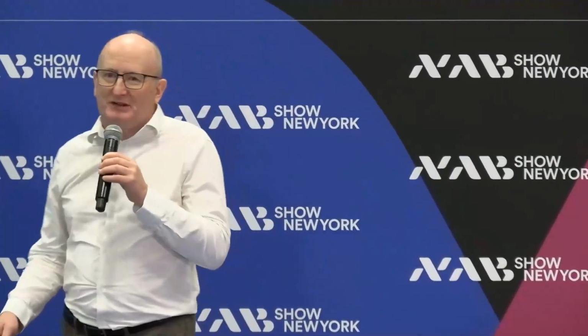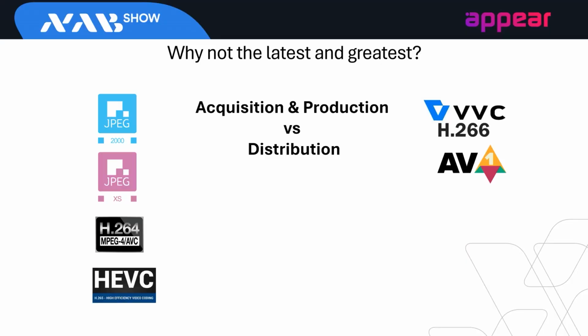Very happy to talk to you about more of these moving forward. On Monday, we did have a discussion about whether we need as an industry to make a forward clocking variant of the AES67, so that we can make the best of the AES67 world, but also have a more robust architecture for how we do audio as we do long haul, especially for REMI. So that's some work, and several other industry players I've been talking to about that moving forwards.